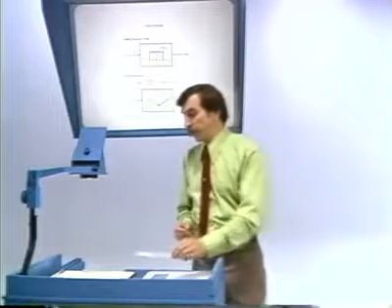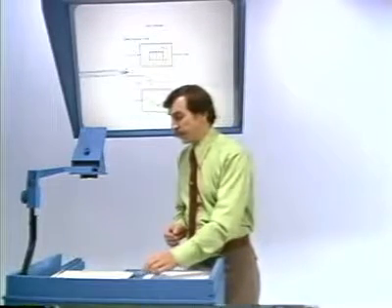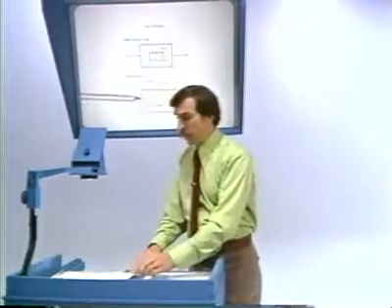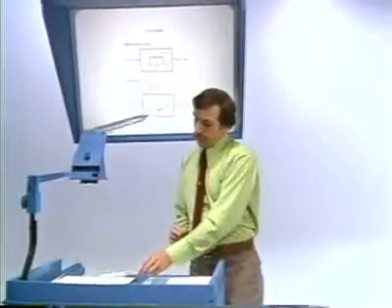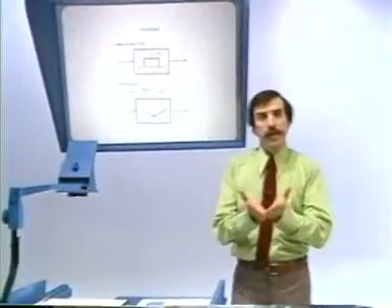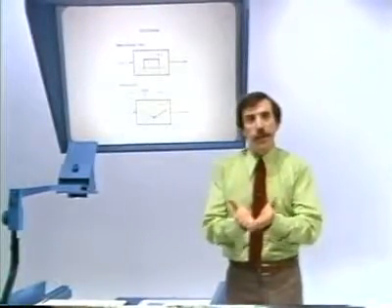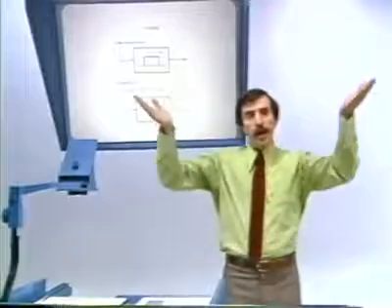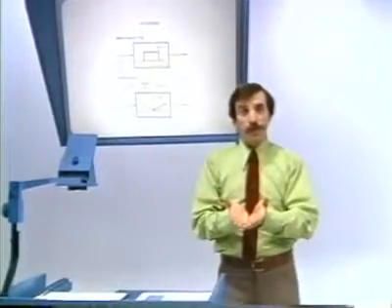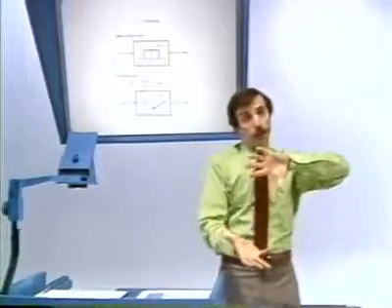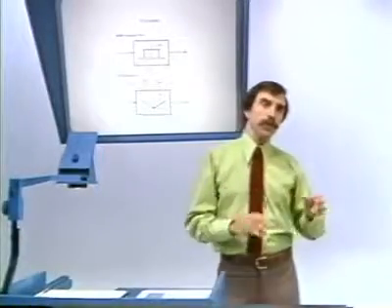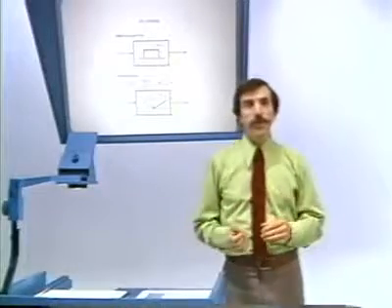Or if we interpret differentiation in the context of our filter, then what's happening is that the differentiator is accentuating the high frequencies because of the frequency shape of the differentiator. Now, recall that this all fits together as a nice package. We expect intuitively that differentiation will enhance edges.